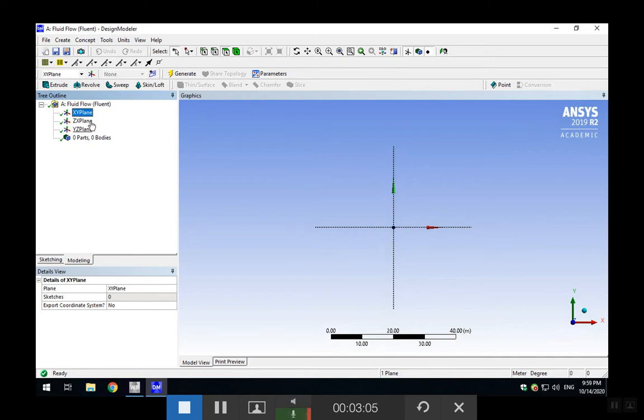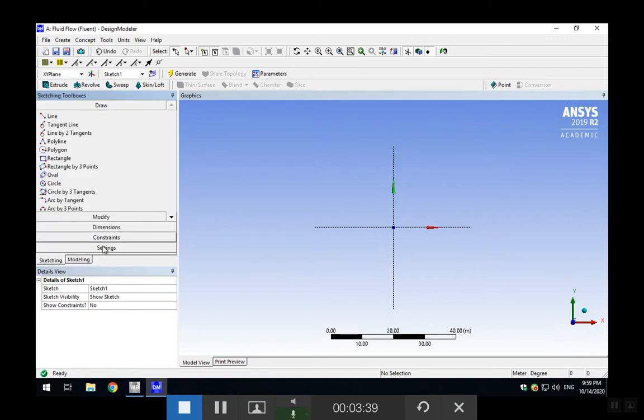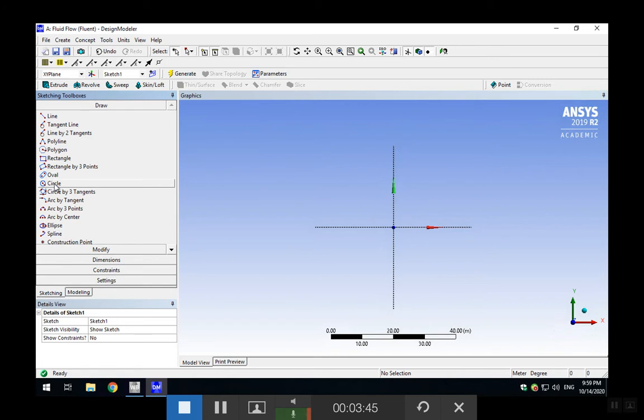So we select the XY plane, then we right click on the XY plane, and you see this thing on top in here, which I'm revolving the mouse around it. If you push this, it's going to create a sketch on the XY plane. And remember, guys, a sketch is just an empty sheet, a white paper that you can draw on. Then in here you go on to sketching, and what we want to sketch in here is a circle, right? It's the base for our cylinder.